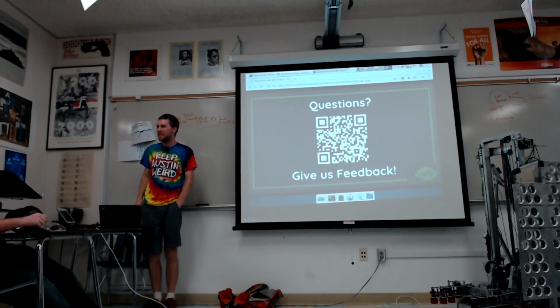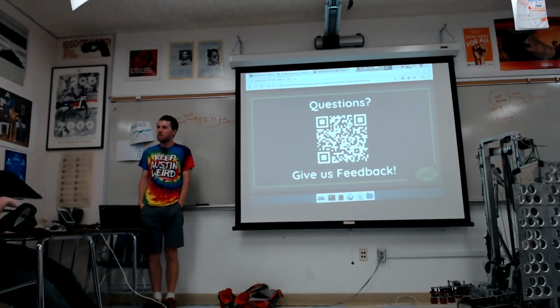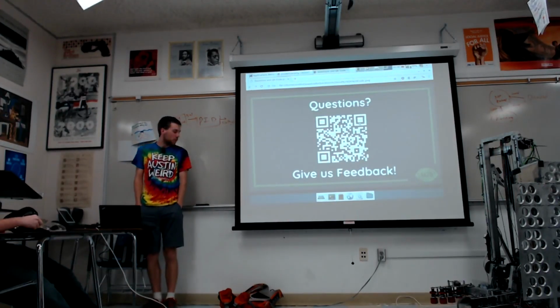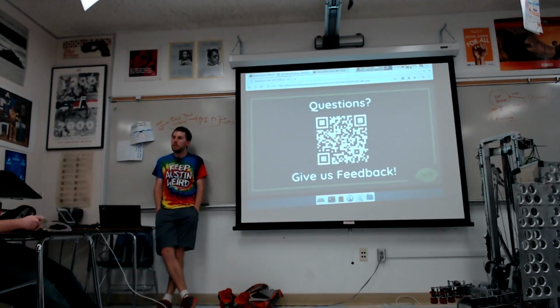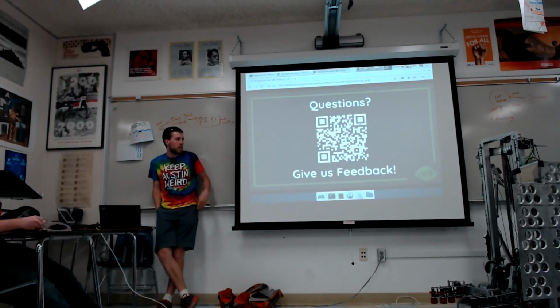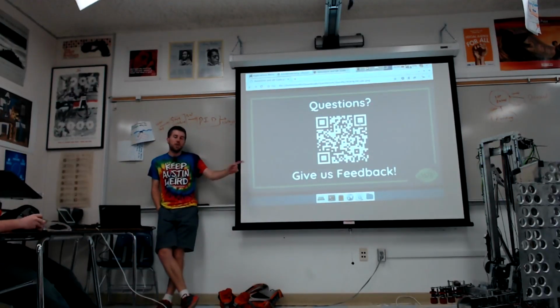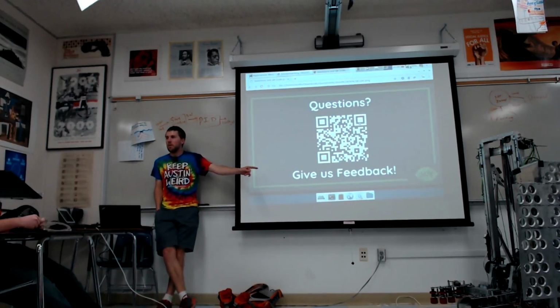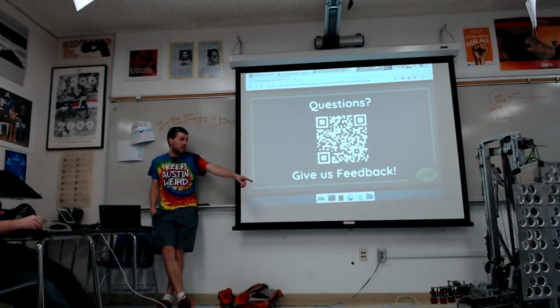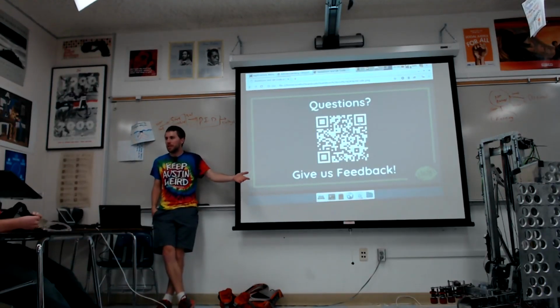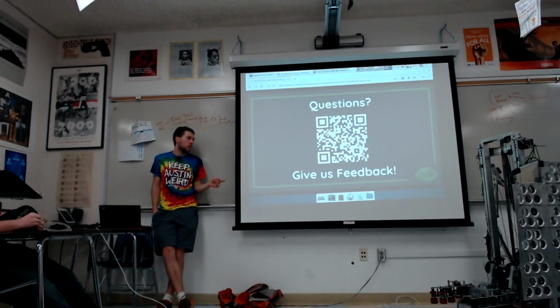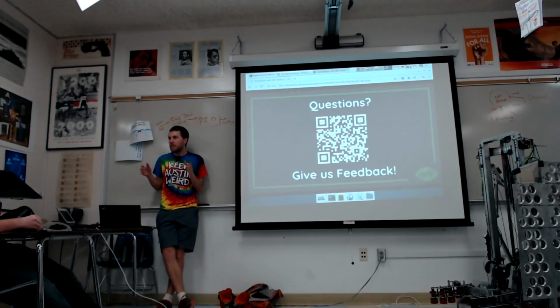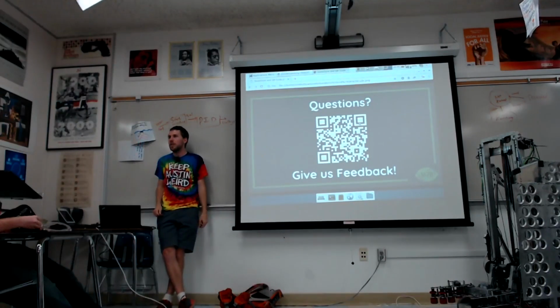So how does tuning other types of maybe more complicated controllers go in the simulation? Much more complicated. Like commercial. Same thing, we can do the same thing. We're assuming our model is reasonable. So if we wanted to be better, we could go into CAD, because the goal is to do this before the hardware exists. Go into CAD and figure out how much all these components weigh, and that should give us a better model for the mass. We could then simulate a motion profile in simulation, plot it, and see exactly what it's doing with our control loop.